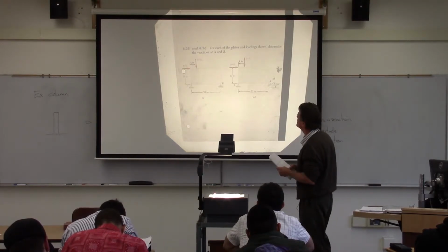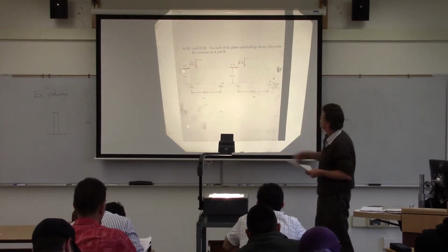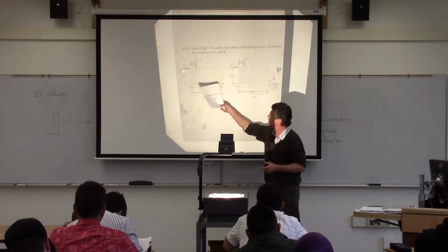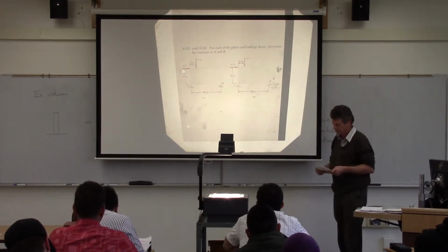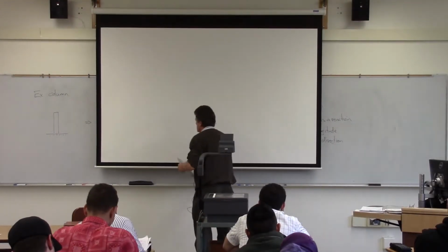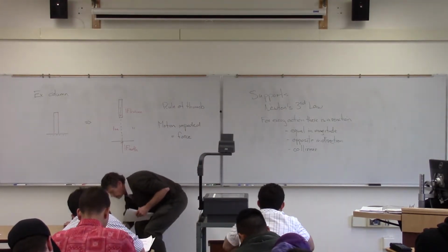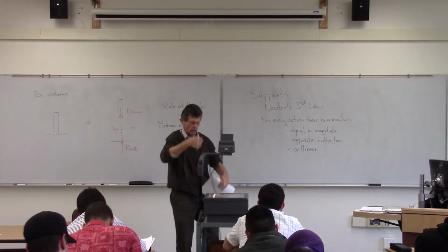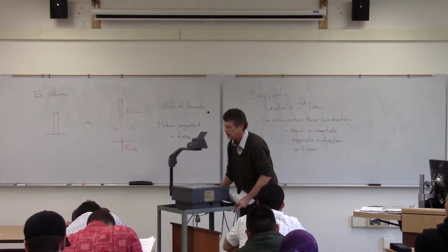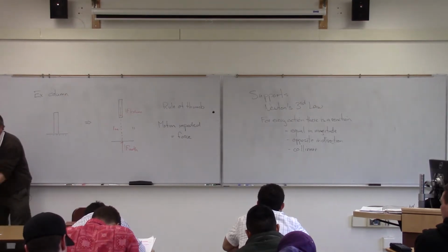Okay. So what we've been asked here is we've got a couple of plates here that have a similar loading on them, both of them there. But our support conditions are a little bit different. We have a pin at A, and then we have a roller at B. So what we're going to do is walk through those steps that we did before with the particle equilibrium. We're going to walk through those steps in terms of setting up a free body diagram that makes some sense to us and that we're then going to be able to create equilibrium equations from.